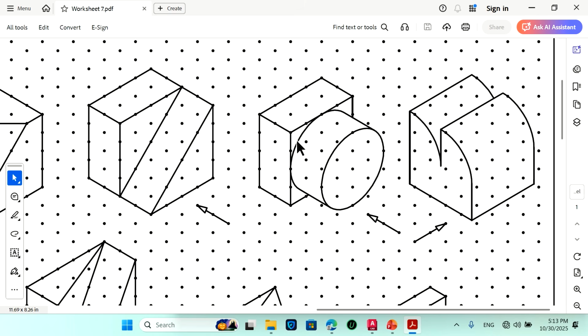So first I will be drawing the principal surfaces. This is the principal surface which is drawn, and the outermost corners are a square. So I need to draw this. The other full square is not visible, because this projection is hiding the other edge. So first we need to start from the front view. The front view is starting from 40 by 40, one square.